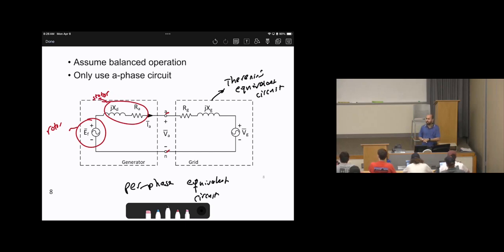What do I mean by strong grid? A more robust grid. In other words, a grid that will not be affected by slight variations. There are some definitions: we call it a strong grid, and there is a weak grid. With a strong grid, when there is any short circuit going on, it will not be affected. It can handle it. The circuit breaker will trip, but the grid will not be affected. If there is, for example, renewable energy fluctuation into the grid, it will not be impacted. It is more robust. Whenever there is any change, it will be just slightly affected.